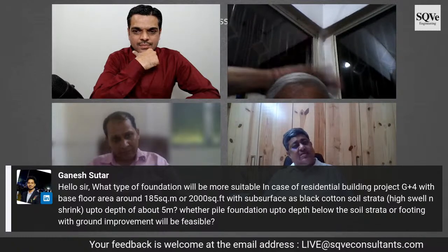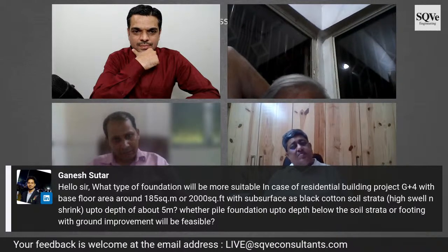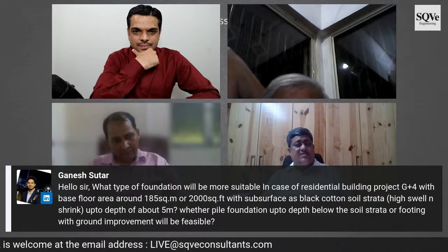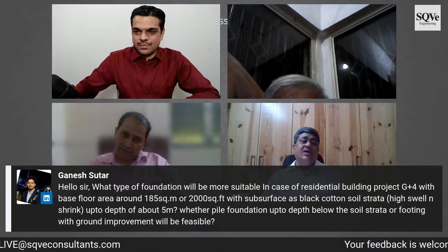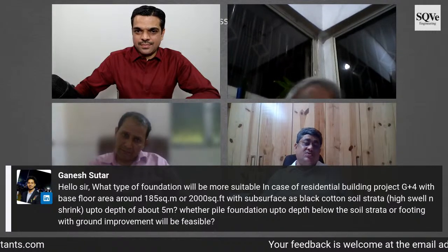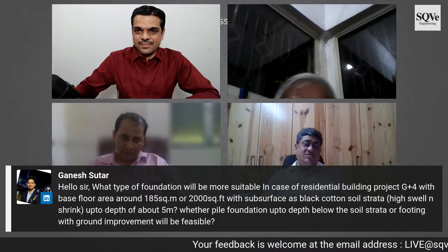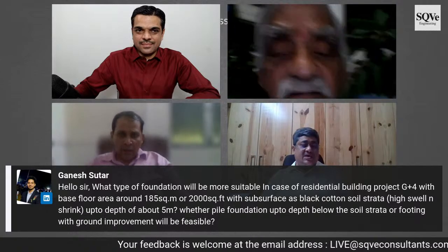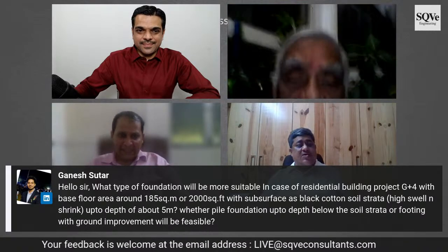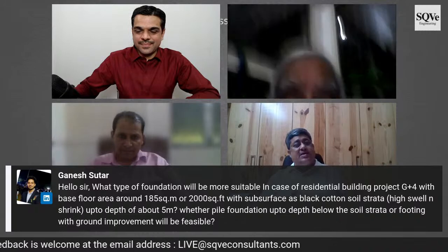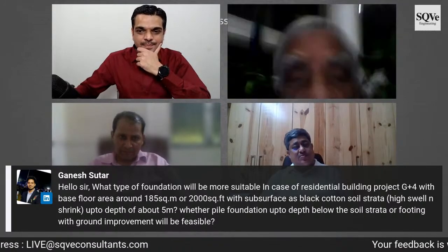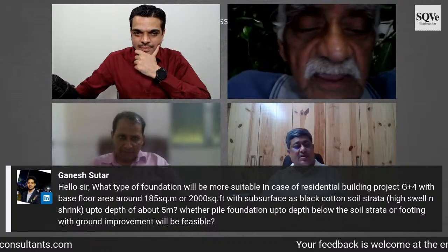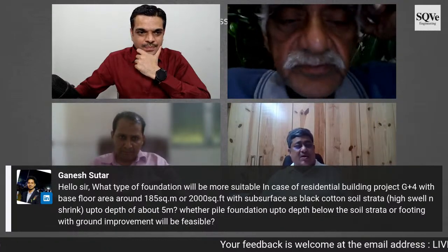We increased the pile length and did without bulb because, as sir says, there is no use when you are entering into a non-cohesive soil. So formation is also difficult. We increase the length of pile, and only friction of the pile is asserted to resist the load. I agree with you.